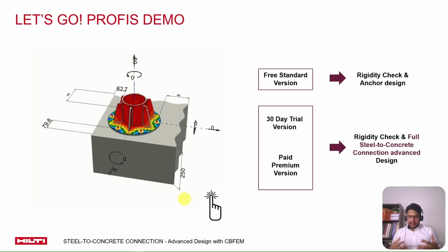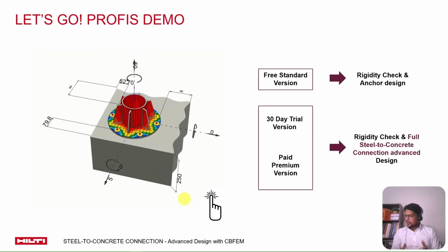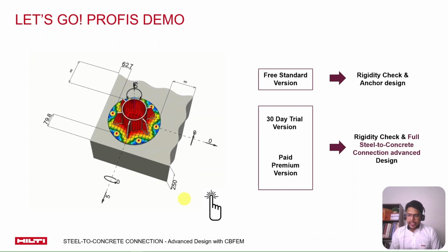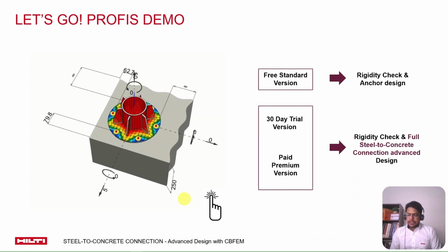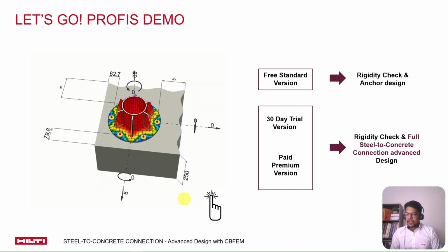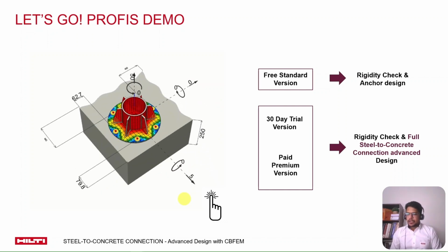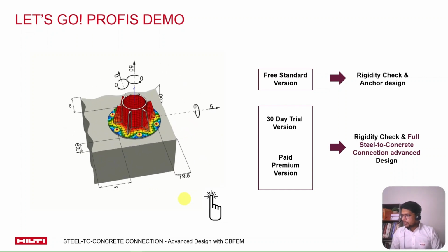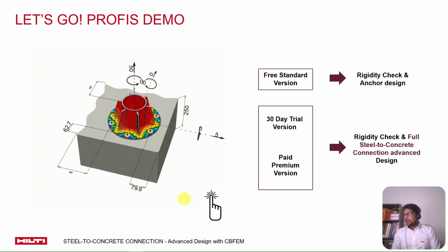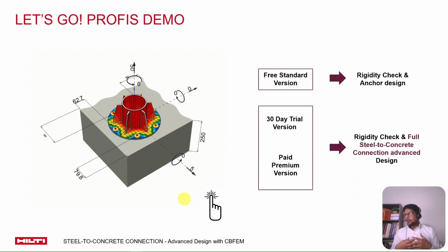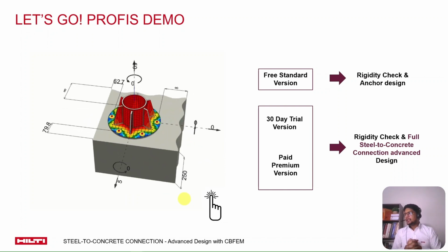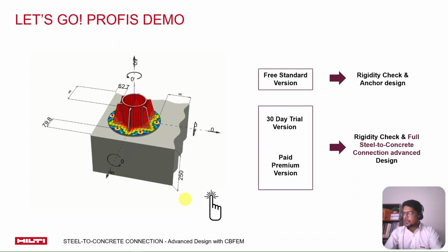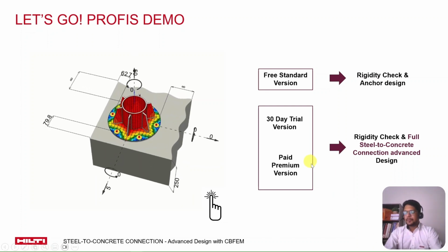In case you have designed your base plate outside of PROFIS Engineering and you just want to check whether the designed base plate is behaving rigid or sufficiently rigid or not, that is something you can check with your free standard version. But if you want to design the full base plate and all its components, then what you would need is the paid premium version.